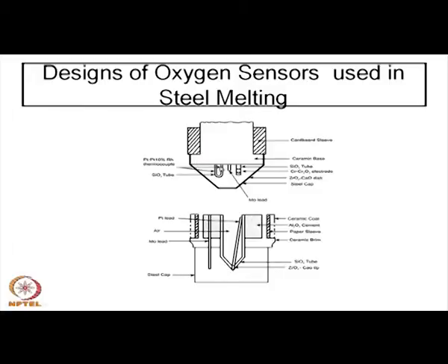These are of course a slightly different design, and you have a small molybdenum wire. Then this is actually a very small tablet of zirconia calcia fitted inside a quartz tube. So, it has been sealed. The whole tube is not made of zirconia because it becomes costly. So, instead, certain sealing technology has been used, so that at the end of a pure silica tube one can have a tablet of zirconia, and that tablet of zirconia acts as the electrolyte.